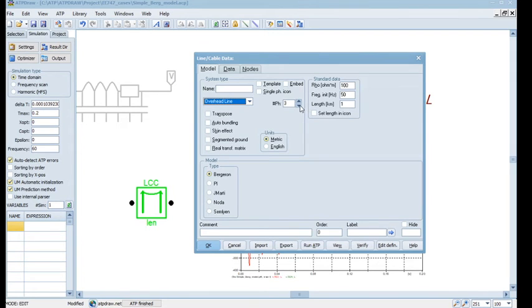These settings maybe we'll see later, but let me just show you what features you have. Over here you have features for including core cable, like enclosed pipe, some configurations of this transmission model. Overhead line is the specialty here. Then the transposition feature, if you want, you can make it. When it says individual circuits, it implies whether in the tower you have double circuit, single circuit, and so on.